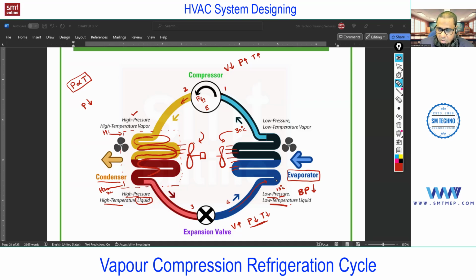So these are copper tubes, and copper is a good conductor. So what will happen? The temperature of the surface of those copper tubes will drop. It means you'll get cool copper tubes when the air is thrown on that coil. Okay, on that cooling coil, what will happen? The air heat will be extracted by the refrigerant. Right? Because again, second law of thermodynamics, heat transfers from high temperature to low temperature.